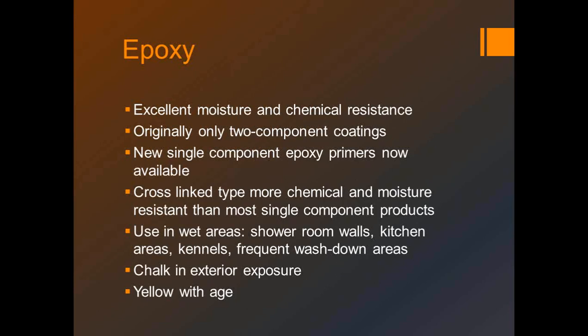Well, the other thing I always think about when putting epoxies on gypsum board is that you're putting a very hard, inflexible coating on a surface that is basically flexible in between the studs. Yeah, you'll still get enough flexibility, I think. I've really never run into an issue where drywall was an issue with epoxy being able to stick to it or getting any kind of undulations or any issues going on with the finish on the drywall.